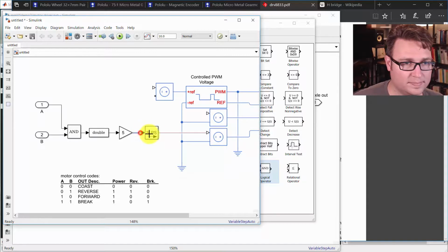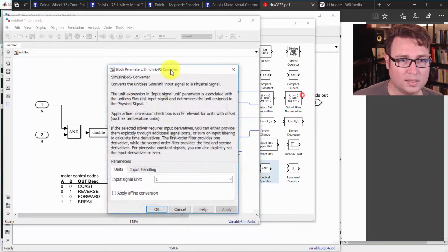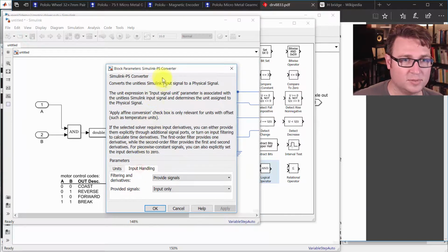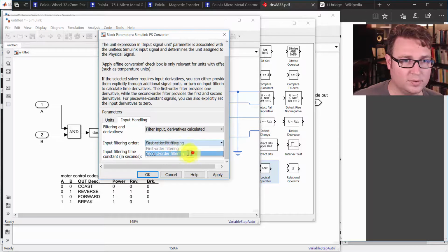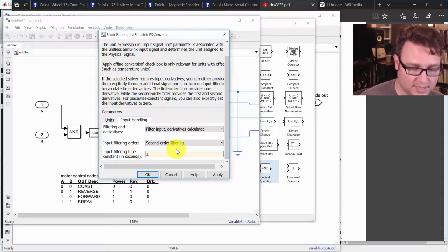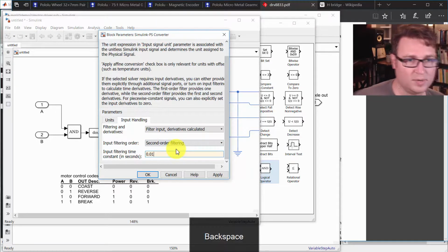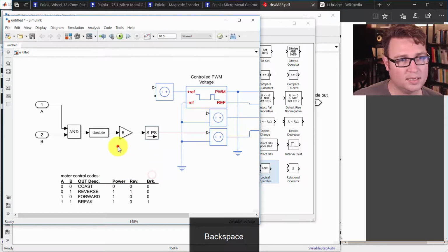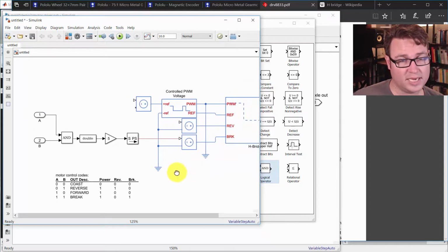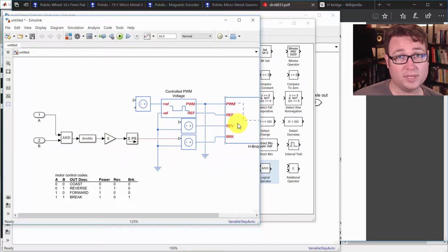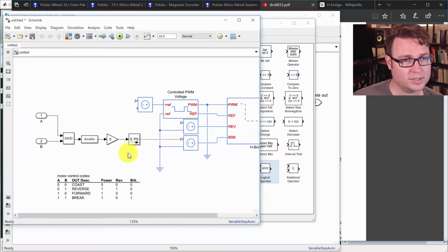Now remember, when we do this, oftentimes we need to make sure that we do a little filtering. So we're going to do our typical thing for this. We'll let it filter at 1/100th of a second, so that if there are discontinuities on the analytical side, the physical side will have a chance of being able to stay with it. It'll be smoothed out for it. So there's that filtering. Alright, very good.